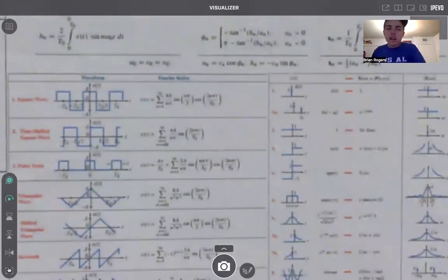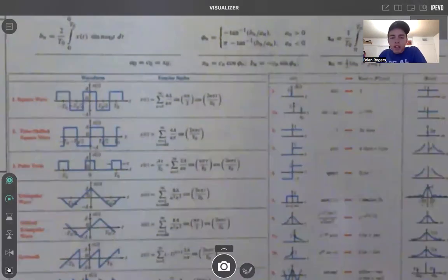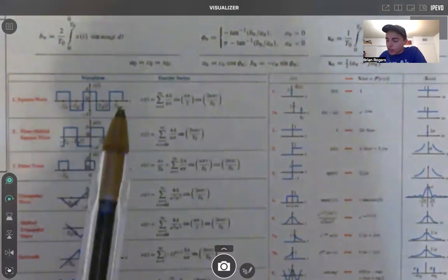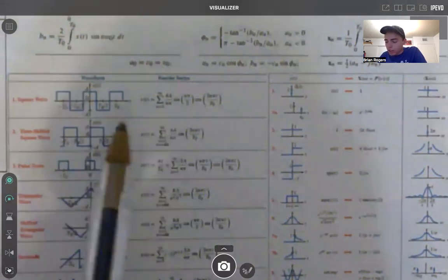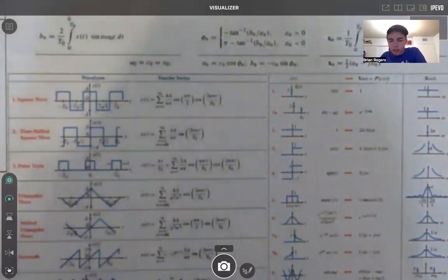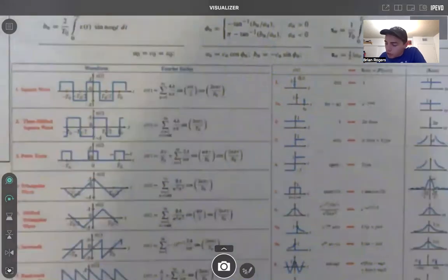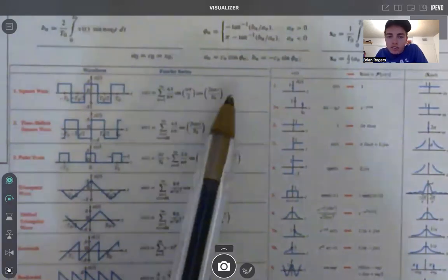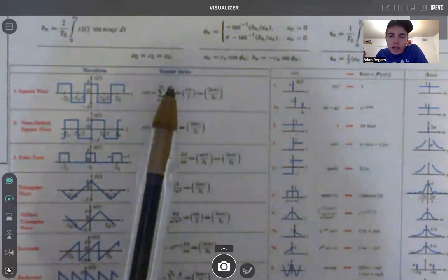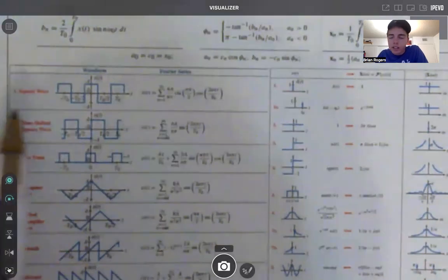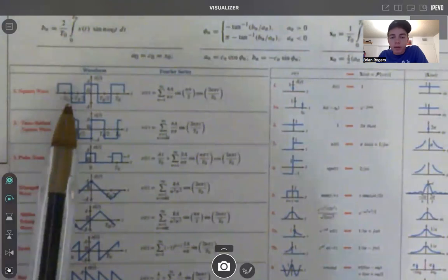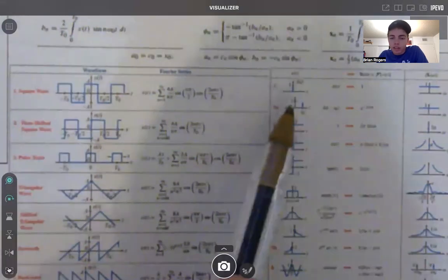Okay, but whatever, you can see the general shape. These waveforms, you'll see them in the textbooks, and they are associated with all these types of signals where you're asked to take the Fourier transform of this. The most important thing is to notice that your coefficient term is given here, but this cosine term added at the end is there because it's an even signal. That comes from the cosine we were dealing with before, where you multiply it at the very end by that last term here.